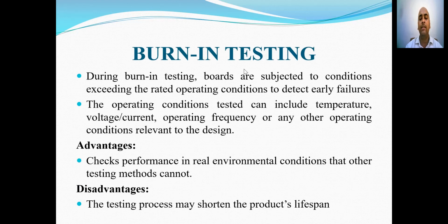Next in the series is burn-in testing. During burn-in testing, boards are subjected to conditions exceeding the rated operating conditions to detect early failures. The operating conditions tested can include temperature, voltage, current, operating frequency, or any other operating condition relevant to the design.